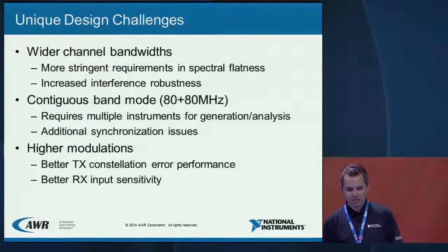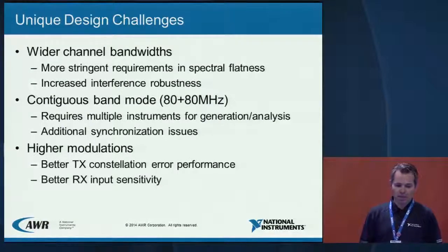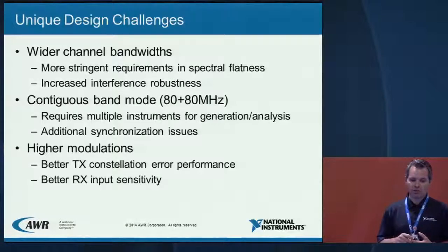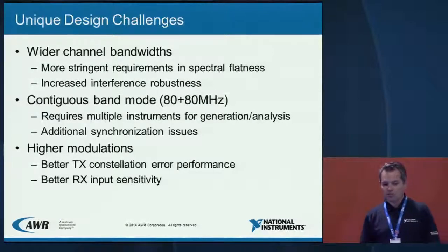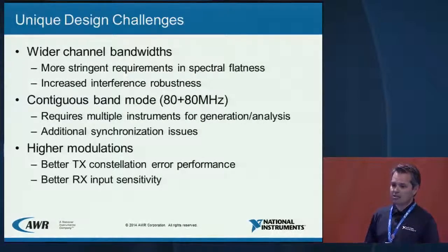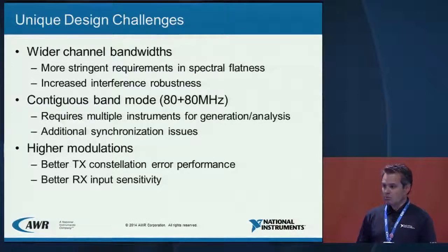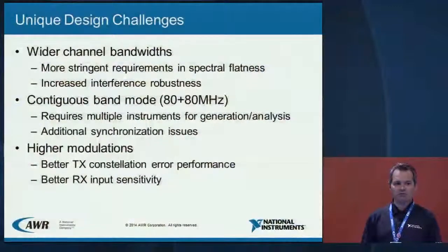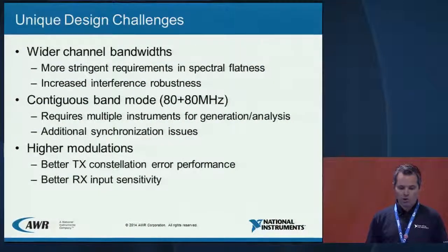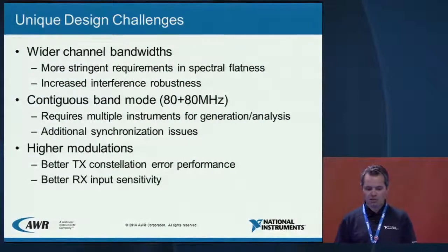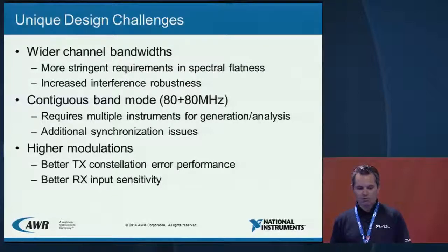The contiguous band mode, the 80 plus 80 megahertz, requires multiple instruments for generation and analysis during development, but that also creates issues with additional synchronization in development or testing of such devices. The higher modulation schemes, as I mentioned, 256 QAM, would require better transmitter constellation error performance, and it will require